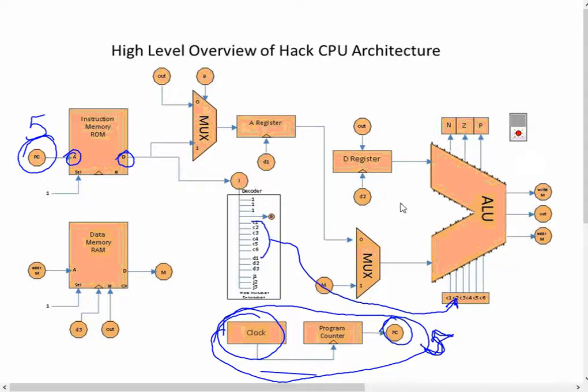The other part of this is what I'm computing. So essentially the ALU has the ability to do 2 computations. By the way, you notice here I've got memory, I have the A register up here, and I have the D register. So if you think about all of those destinations we had, essentially I can compute the A against the D, I can do the D against the M, because this mux is going to select between M and A. So I can do either A or M, right? And then I can do D.